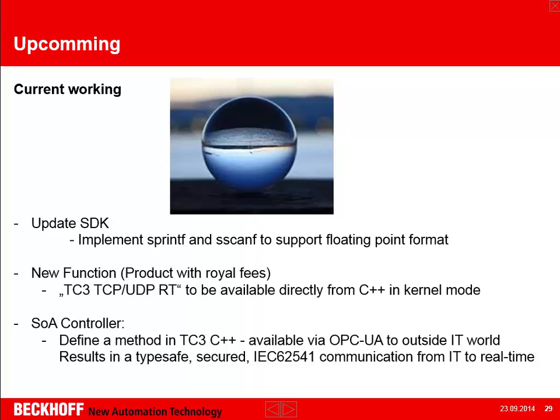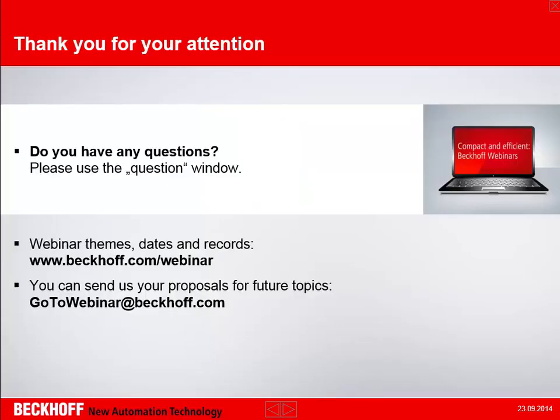And the UA server is internally then executing the method call in the C++ environment. So it's a combination from the non-real-time IT world down into hard real-time deterministic execution.